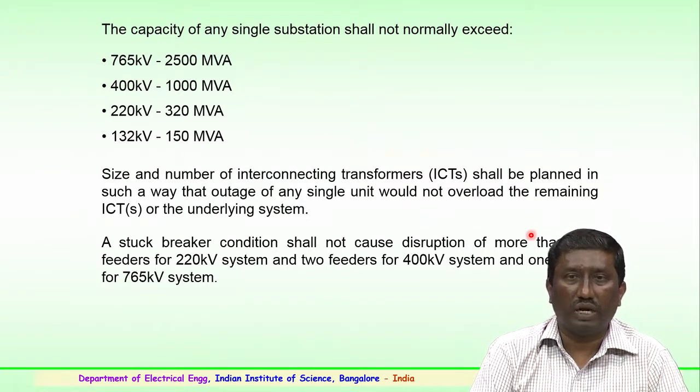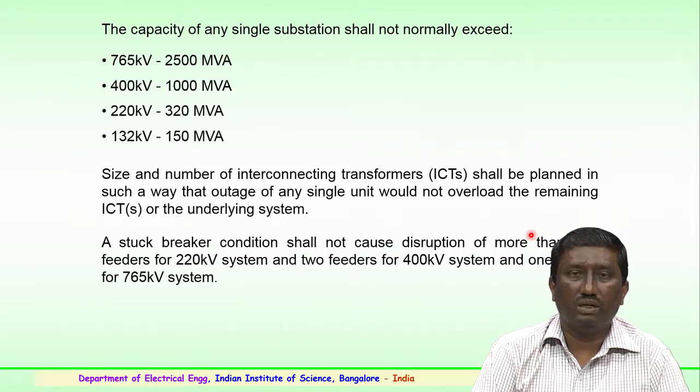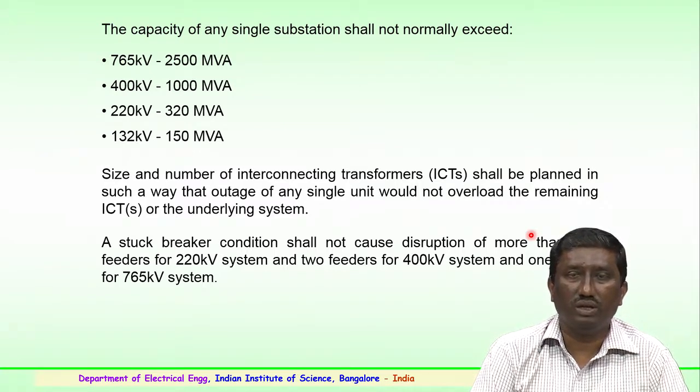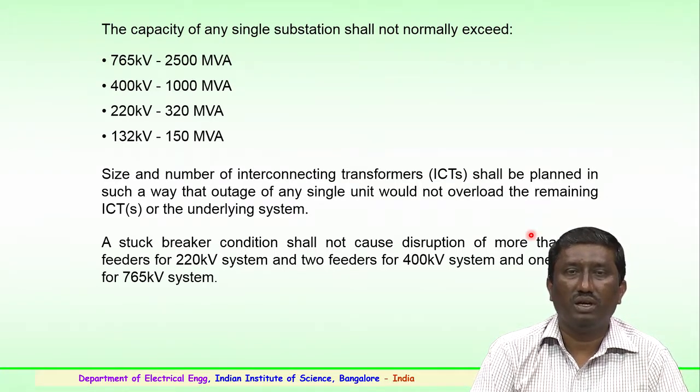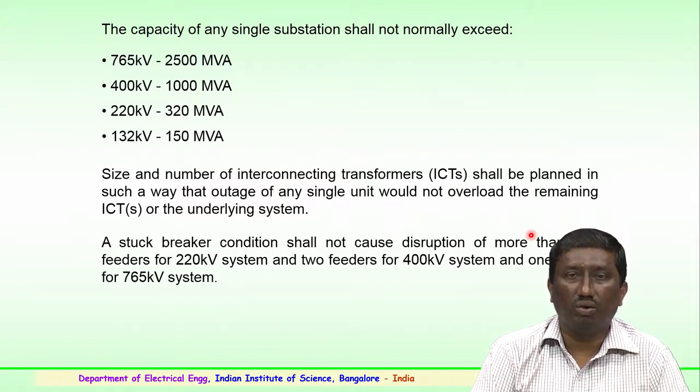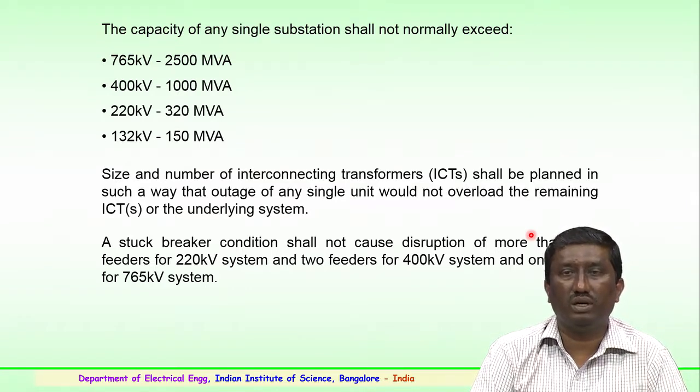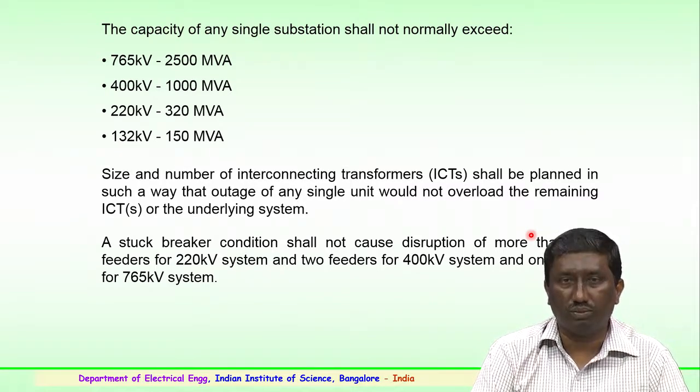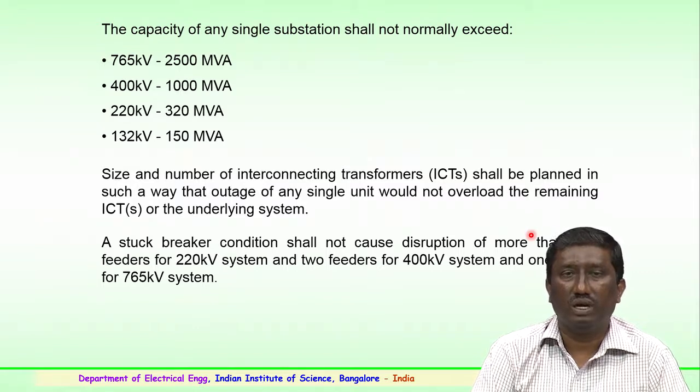This should be planned in such a way that if an outage happens on any single unit, the other transformers are in service, and this should not overload the remaining interconnected transformers or the underlying system. That is a point to be considered.